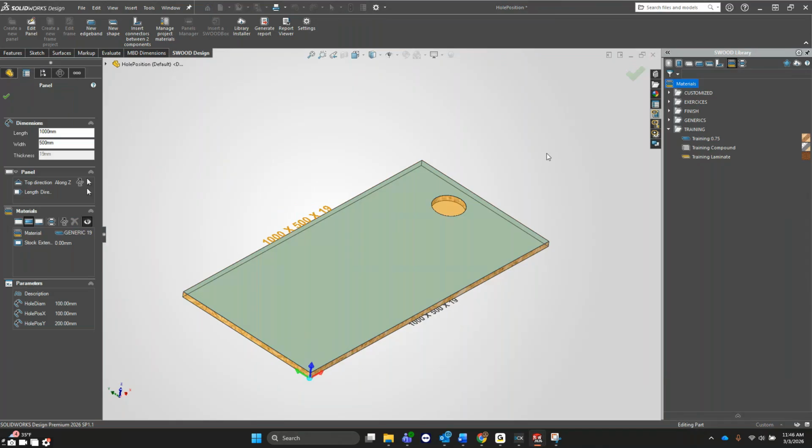When we get more into our frames, what a frame is, is kind of like a blank assembly that we can insert panels and hardware and anything else into to build an assembly, like a cabinet or something like that. And when we do that and we put our panels in, we'll resize them inside of the frame to get the sizes of the cabinet that we want.